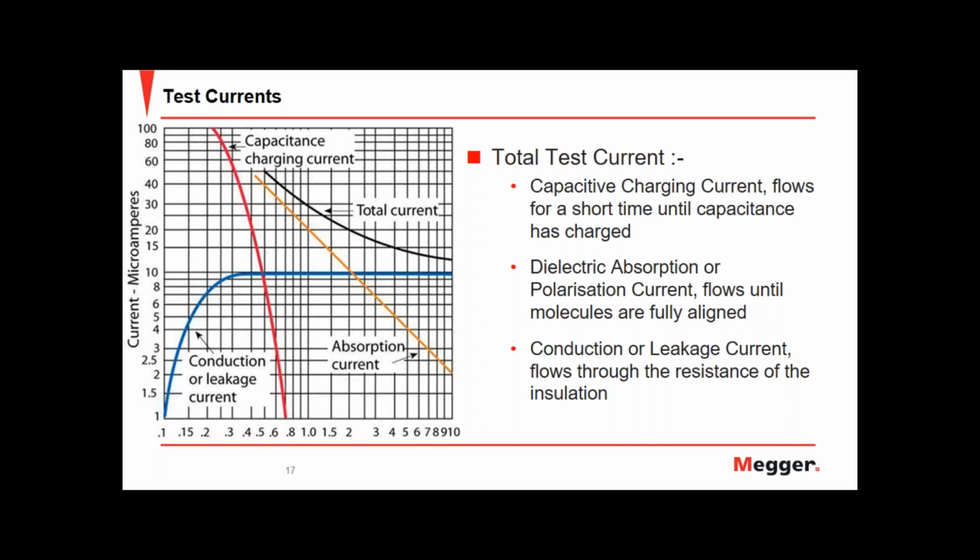This sort of goes back to the question that we had earlier a little bit. We tend to use the positive on the ground. We tend to want to do that because of electroendosmosis. It's a bit of a carryover from some of the old cable types, but it's been convention that we've used, and we continue to use it.